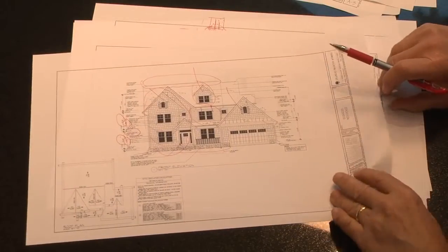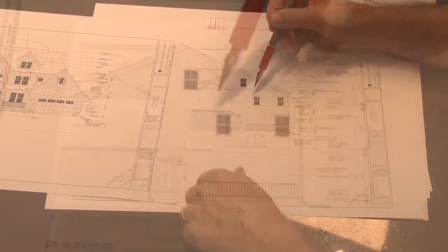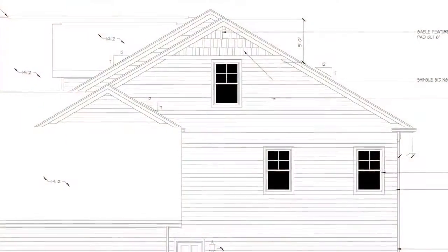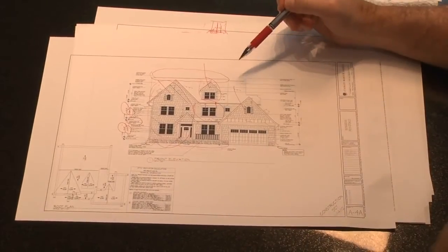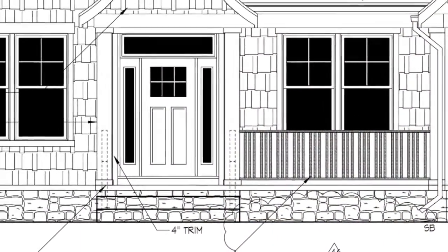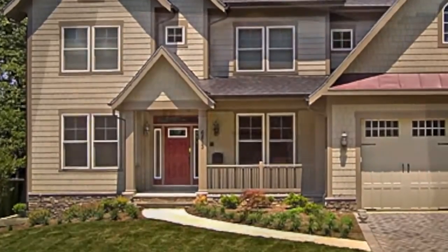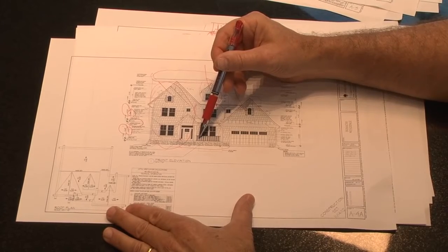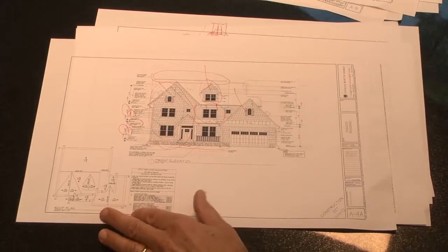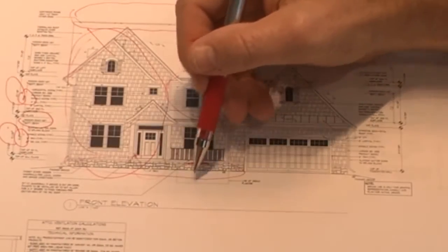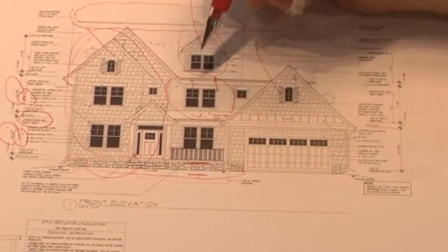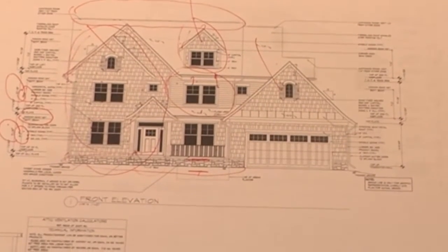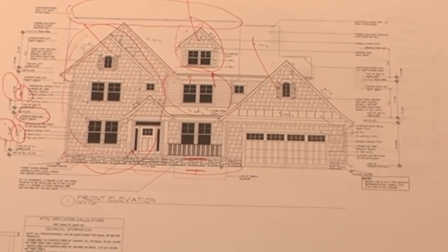On the side elevations, we typically will do 4-inch surrounds, so that we are picture framing the windows, but the presentation's a little bit more subtle on the sides and the rear than it is on the front elevation. Here you see the porch. Our columns are all PVC columns. Rails are optional. The only reason that you would need to have a rail, other than if you just like the look, is if the grade from the porch to the ground is more than 30 inches by code, we're required to put the rail in, and in that case you would be required to select the option.